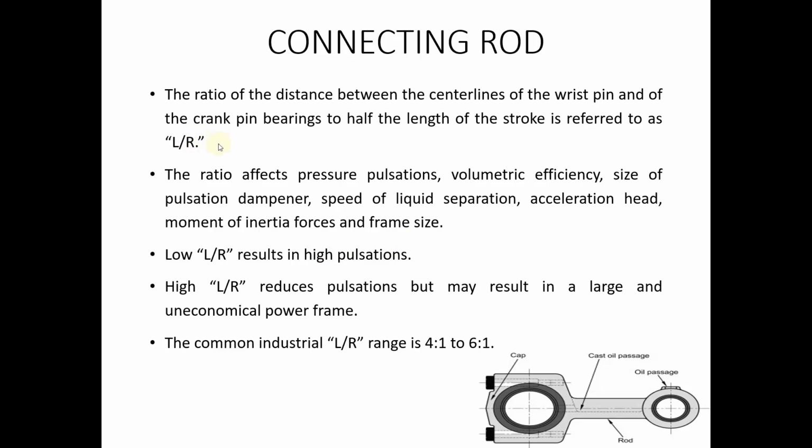So this ratio affects the pressure pulsations, volumetric efficiency, the acceleration head, then the forces such as moment of inertia forces, and frame size. So all these are affected by the L by R ratio. So that is why this ratio is very important.